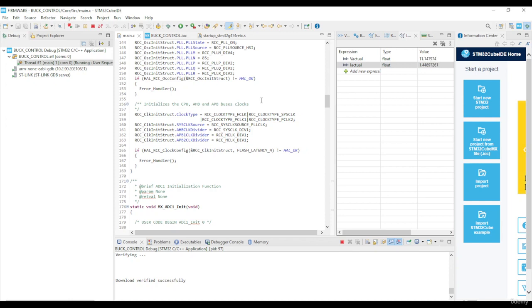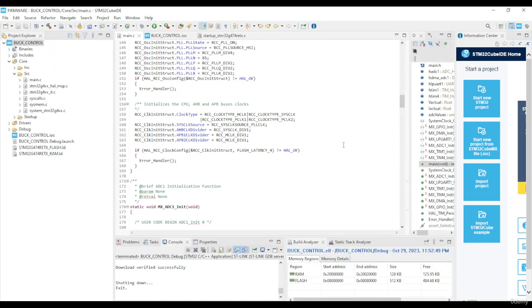So in your application, you shouldn't close it here because you're not sure what it might default to. It might default to 100% duty cycle. So what you want to do is turn everything off first. Make sure you have 0 volts in the output, and then you can turn it off there. And then you should be sorted.